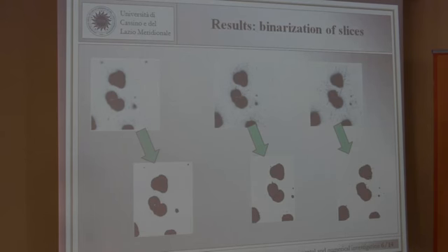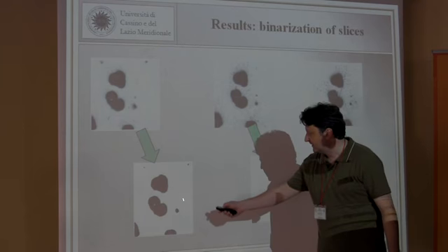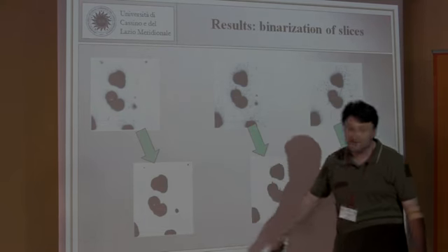These are the results of 3 different slides taken in the optical microscope, 1, 2, 3. Then we have the image processing results, characterized by finding a threshold, and then we binarized the photos, having a matrix completely white and graphite completely black.